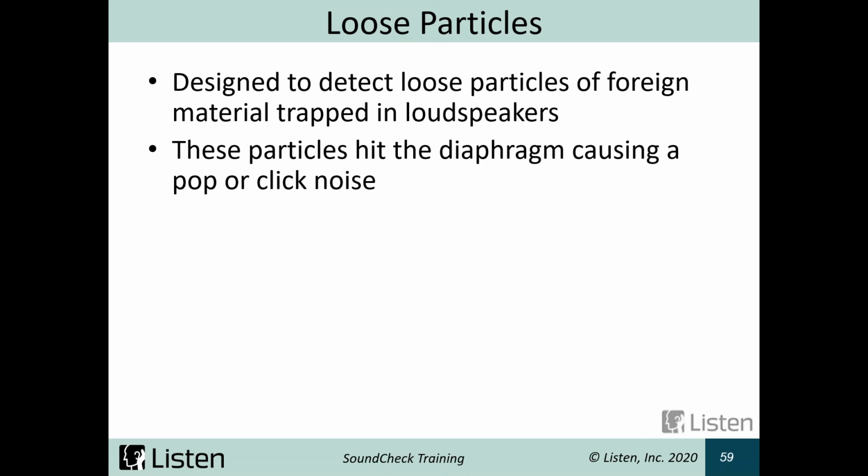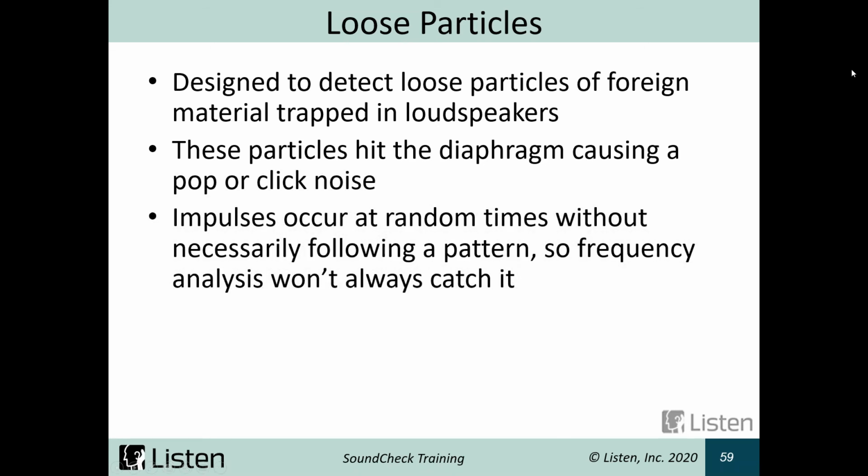Loose particles was an algorithm designed to detect loose particles of foreign material trapped inside of a loudspeaker. When these particles hit the diaphragm, they'll cause a pop or click noise. These impulses aren't really frequency-based. They're going to occur at random times, so trying to use frequency analysis won't always catch them. If I just wanted to use THD, it might not always find these types of transients.